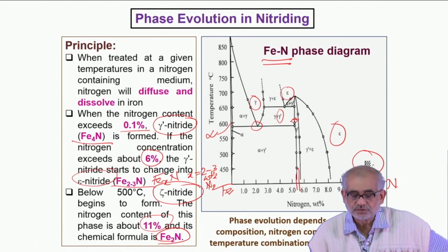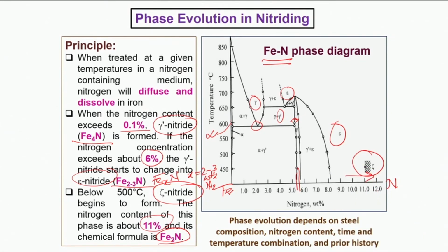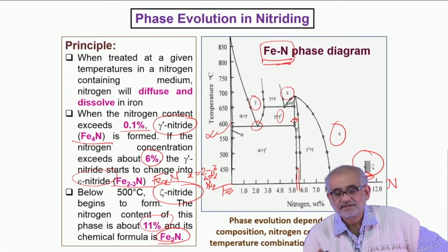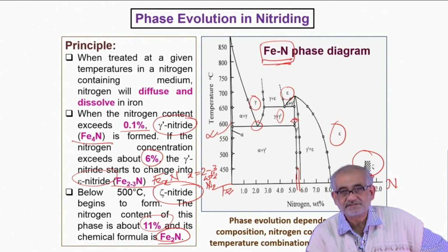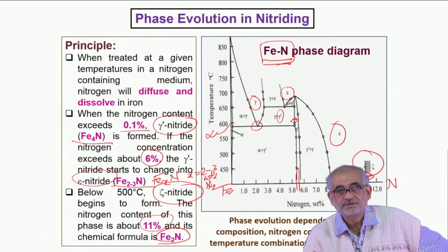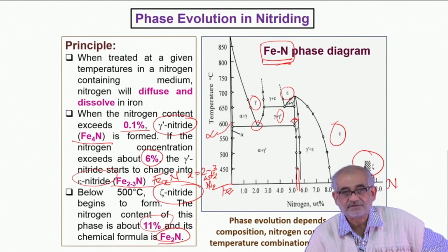not even shown. So we must now reposition ourselves and move away from iron carbon and think in terms of the iron nitrogen diagram, and realize that there is very little solubility of nitrogen in alpha iron. By the by, we did make a brief mention, while discussing the formation of various phases or microstructural evolution in one of the lectures, wherein I did mention that alloying elements in iron or in steel can be divided into 3 categories: ferrite stabilizers, usually the BCC elements; austenite stabilizers, usually the FCC elements; and a part of the BCC elements which have a very strong tendency of forming carbides, called carbide formers.